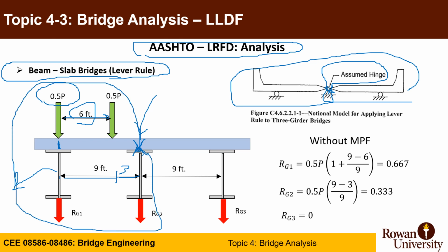Take the moment around the hinge to get the reaction in girder 1.